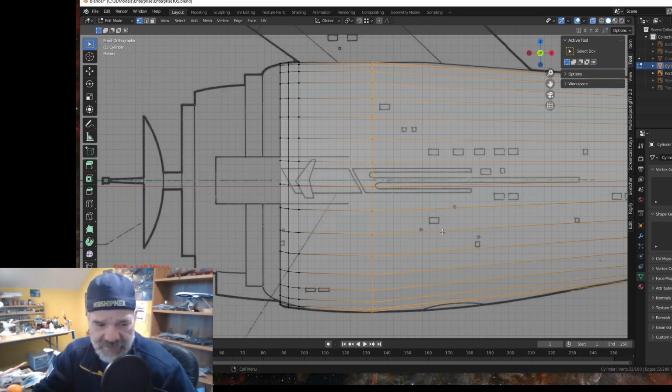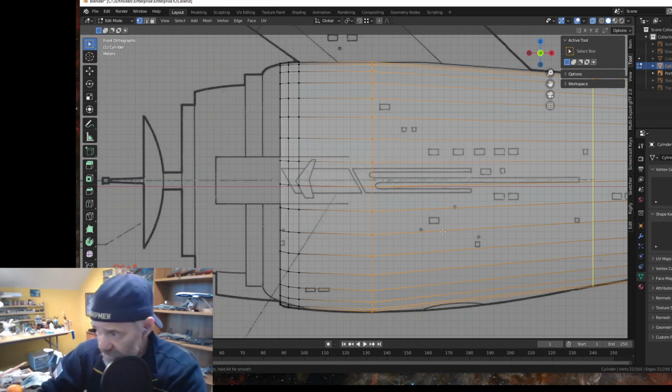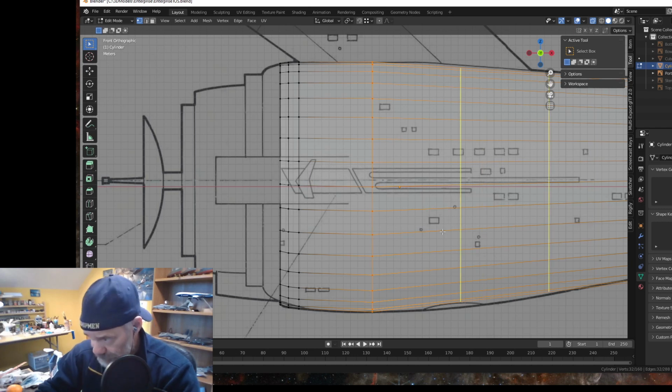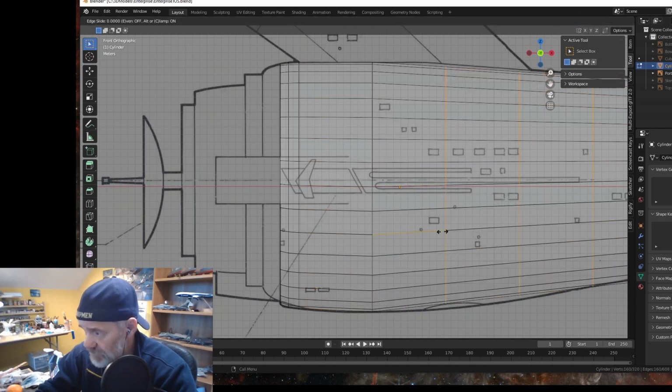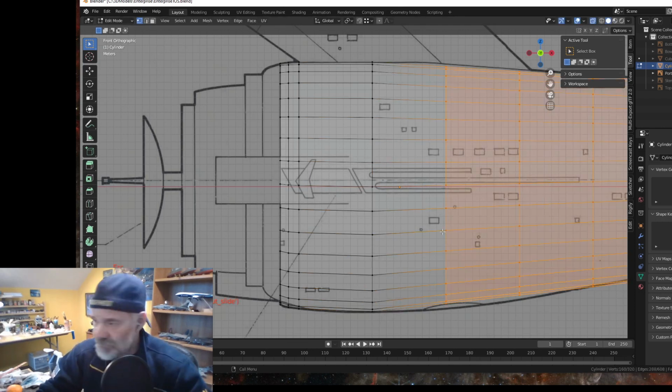And we can add, now here's another thing. You can Control R, get the loop cut going, but before you click, you turn your mouse wheel and add sections. All right, so I have 4, I think, and then escape so we don't move them.